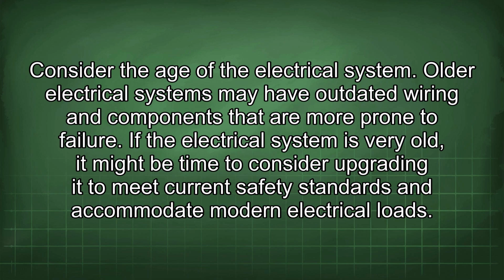Consider the age of the electrical system. Older electrical systems may have outdated wiring and components that are more prone to failure. If the electrical system is very old, it might be time to consider upgrading it to meet current safety standards and accommodate modern electrical loads.